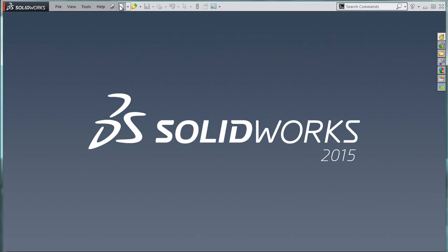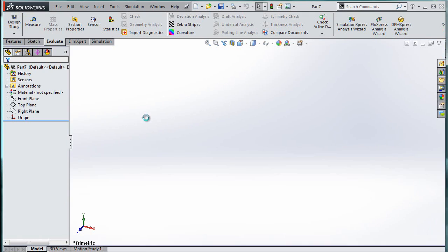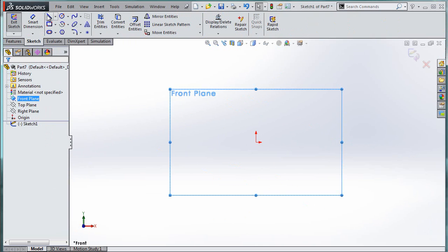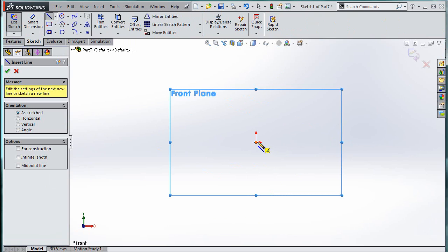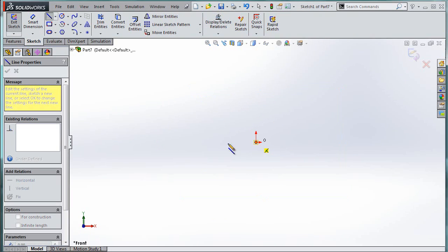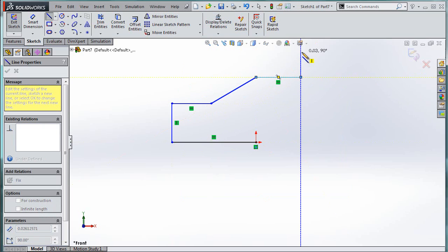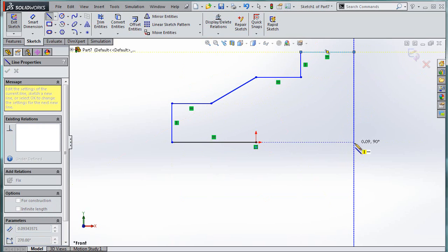So now we're going to have some fun in SolidWorks, so create yourself a part. It's going to be very exciting. Yeah, all right, so I'm going to sketch off the front plane, and I'm just going to draw that first image. Make sure you start at the origin. This is one of those things where the origin really matters, because the center of mass is of course relative to where the origin is, so if your origin is in the wrong spot, it's not going to work. Make sure that this line is horizontal. Make sure those are collinear if you can. We can fix it later. Beautiful.